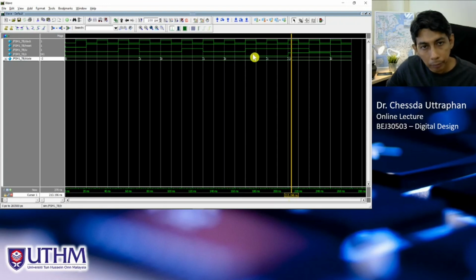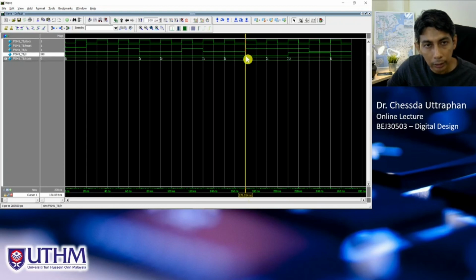But here, because we have W equal to 1 here, right? 1 here, and the next measurement is still 1, so it will go to state B from A here, and then because this is still 1, it will go to state C, and at state C, of course, we have Z equal to 1.